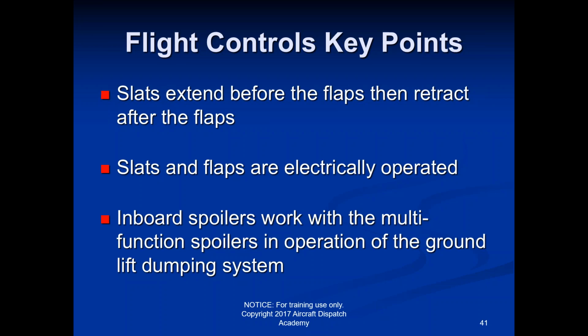So right when you touch down, even though there's weight on the wheels, it's usually not a lot of weight, because the wings, even at that point, just due to the speed of the aircraft, are still supporting the majority of the weight. Even when the plane is completely wheels on the ground, all three, with your nose down and everything, as long as the plane is still moving along, it's still supporting 3/4 of the weight of the plane. So even though all the wheels are on the ground, the weight of the plane still is not fully on the ground.